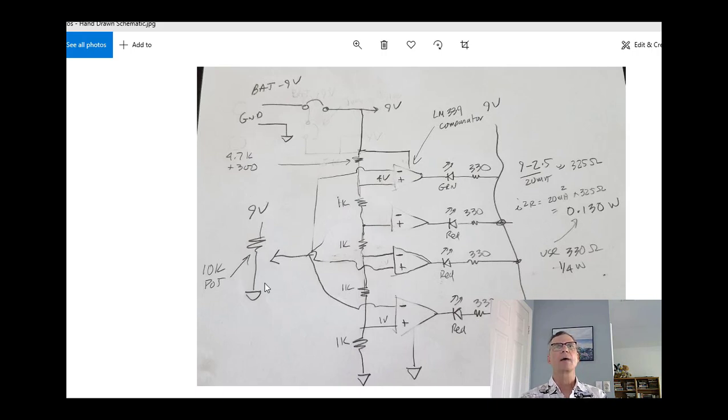I'm going to use a potentiometer, and easy to draw a potentiometer, but I got to figure out exactly which one I need because I'm going to need to lay down the right footprint on my board. So our next step from here is we're going to actually draw this schematic in KiCad.